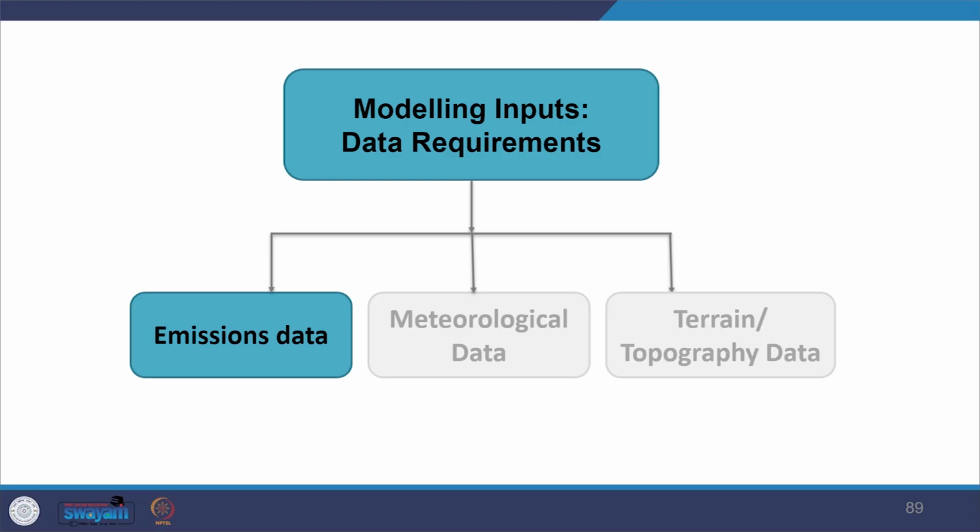Emission rates need not necessarily be exact. So for this purpose, you need not take the exact value, as the likely impact of a plant development could be assessed by using the highest likely emissions. So you can take the highest emissions also, and you can do the prediction. The highest values could be like maximum emission limits defined for operational purposes. So for those figures also you can take them and do the calculations.